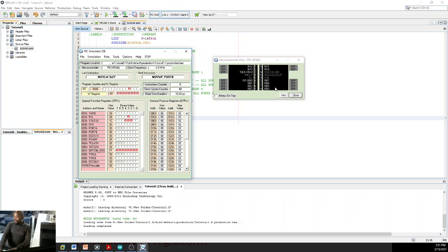We are going to write FF to these pins by writing to port B. When we write FF to port B, all port B pins are high, and the port B register has FF on it, right? Now the next thing is the endless loop: main, go to main. That's the end of your program, right?